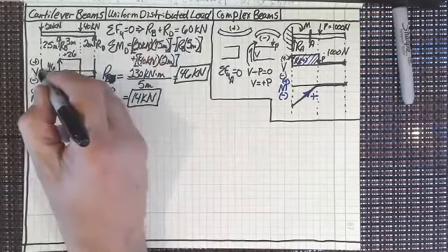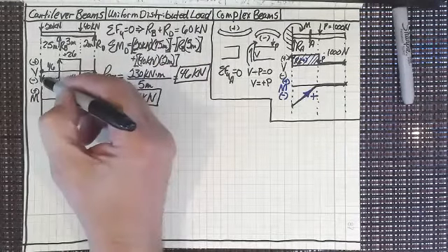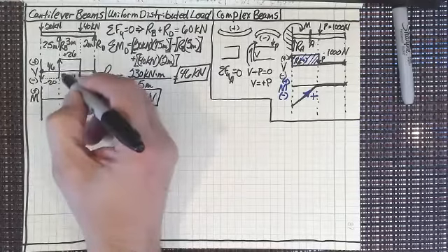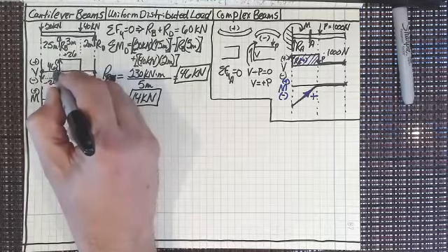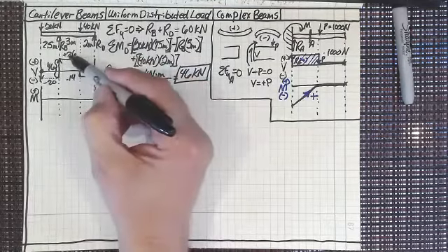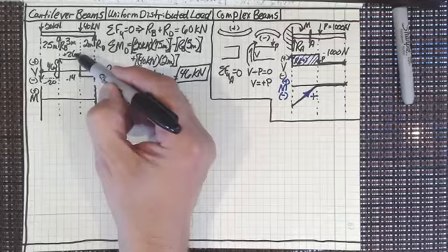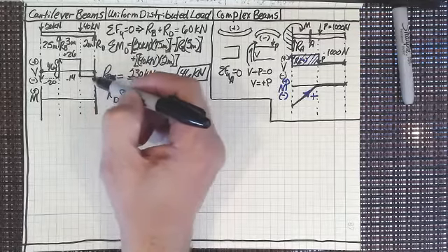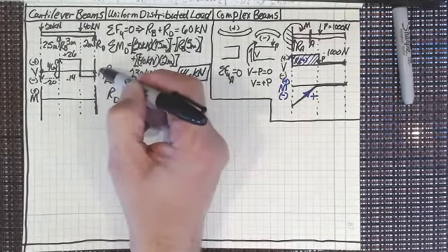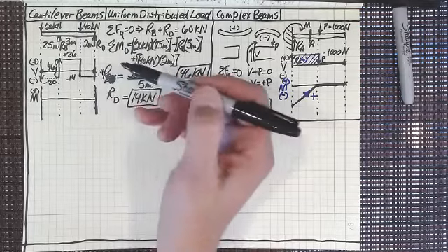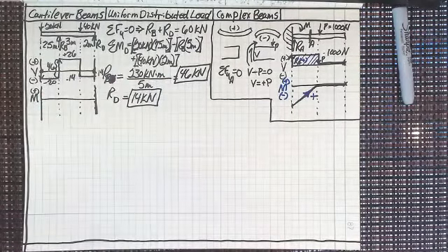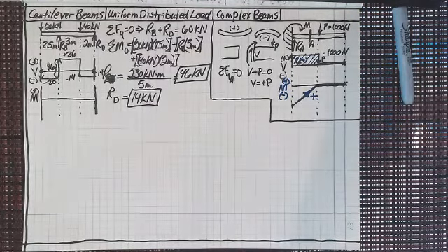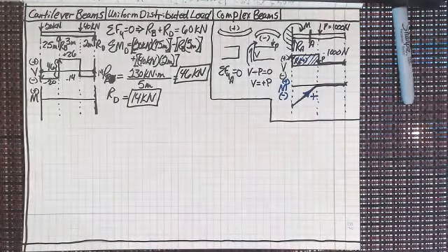So we start at 0, we go down 20, minus 20. And then we go up 46. I should put a little squiggly line there. And then we're at 26, and then we go down to minus 14, across minus 14, and then up 14 back to 0. And that's our shear force diagram. At any point, we can tell exactly where we are and what we're doing. I'm just going to crosshatch that so that everybody can see.